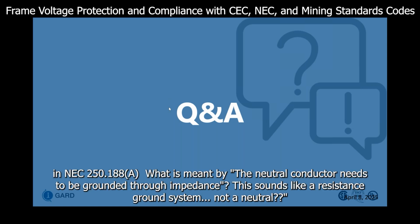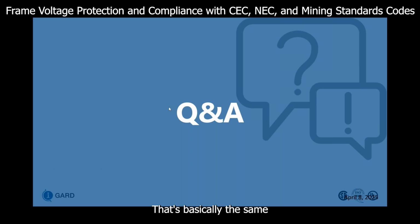In 250.188(A), what is meant by the neutral conductor needs to be grounded through impedance? This sounds like a resistance grounded system. That's basically the same as what they're stating for a resistance grounded system. So that's what that means based on the question that you asked.